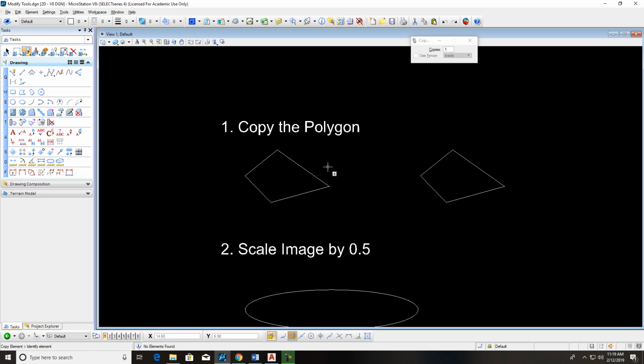Something else I want to make sure you know is that right now it's wanting to do this again. It's got the copy command up, and when I go into the next command, it changes. It'll stay up there because this one doesn't work off escape, if you're used to Autodesk products. So when I come over here to element, let's say I chose this and it's lit up, and I want rid of that. You can right click, but you can also, whenever you click on it, hit deselect. This right here is your clear, and it takes it off of your element select.